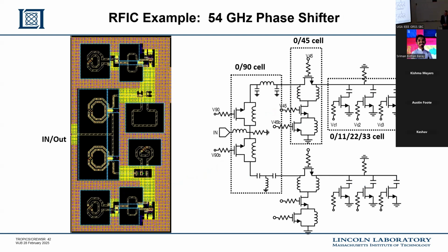Okay, so that was the radiating side of the reflector array. On the back side are these RFICs. They're phase shifters for the 23.8 band, the 31.4 band, and the 50 to 58. So here's the 50 to 58. What's going on here is it's a 4-bit phase shifter.